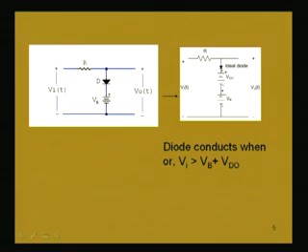This Vb is already there. So, Vb, and again this is the diode drop. So, they are in series, totaling up to Vb plus Vd naught. So, the potential at P must be higher than Vb plus Vd naught. When this happens, only then the diode will conduct. So, whenever Vi is greater than Vb plus Vd naught, then the diode will be conducting.